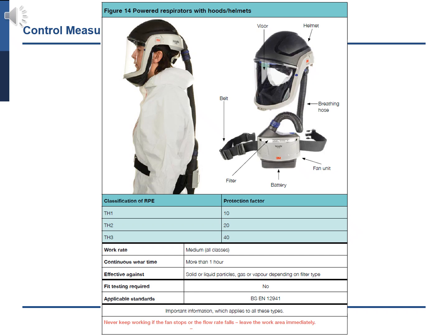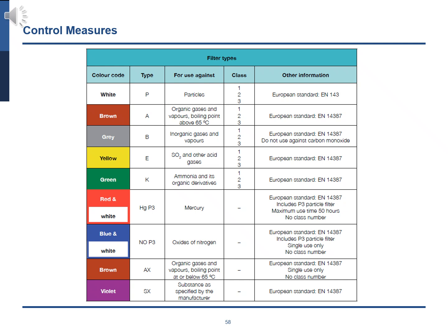Important note: if the fan stops or the flow rate falls, stop working immediately and leave the work area. Filter types and usage guidelines. White, P4 particles. Classes 1, 2, 3.